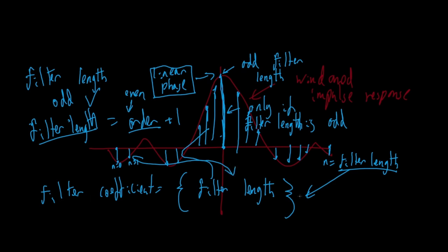A longer filter length means a longer array, which requires more computational power because there is more mathematics to do. At the same time, more filter coefficients means you capture more of the impulse response, which means better filtering performance.